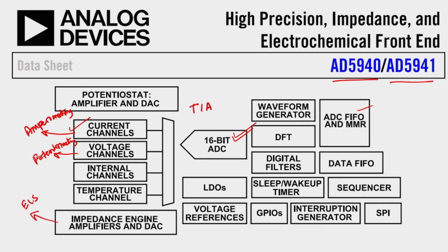These are the electrodes that are required, reference electrode, working electrode, all the electrodes that are needed for electrochemical sensing. I can insert them, program it, and test it. Once I am happy with the program and the application, then I can design my own PCB with the same chip. I just need to transfer the program into the chip, so I don't have to do the programming again. That is the typical design phase, where you use the evaluation board to test the whole process.